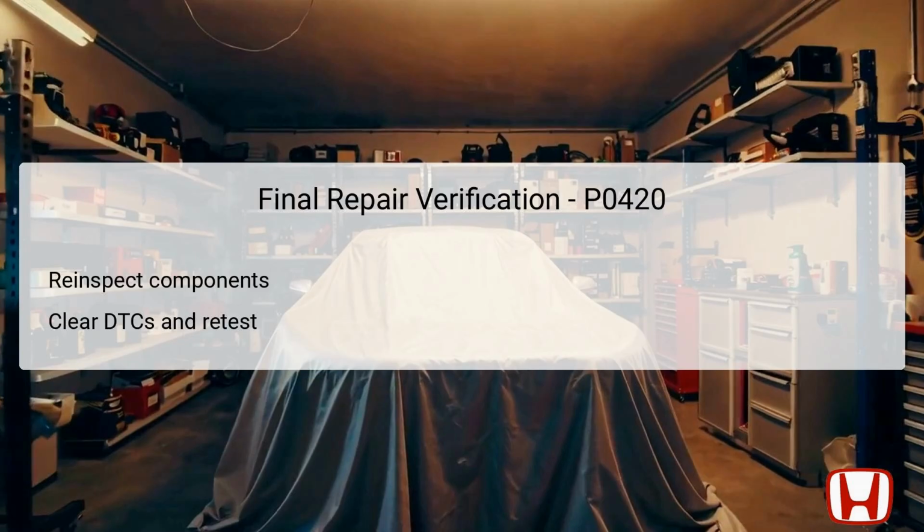Once you are satisfied with the checks and repairs, clear any stored Diagnostic Trouble Codes, DTCs, using the diagnostic tool. Following this, retest the vehicle under the same conditions used during the initial troubleshooting stages, allowing the PCM to reevaluate the performance. Observing the status of DTC P0420 and the response of other related sensors during this retest will confirm whether the repairs were successful and if the catalytic converter is now functioning efficiently.